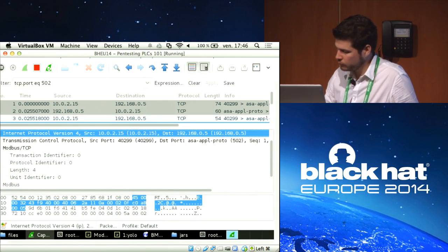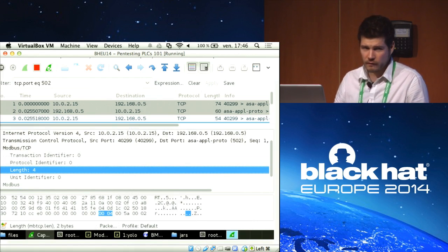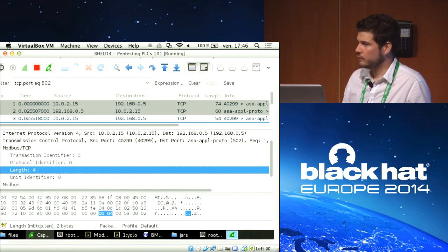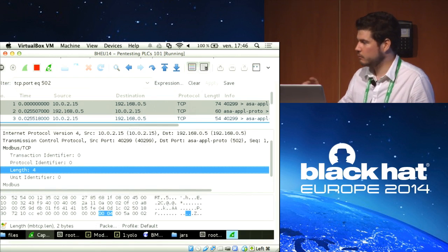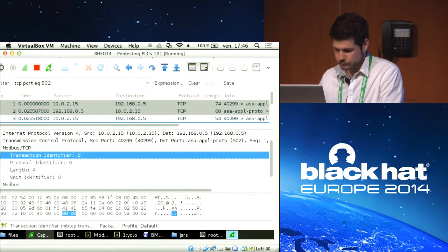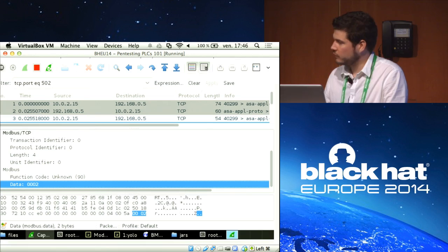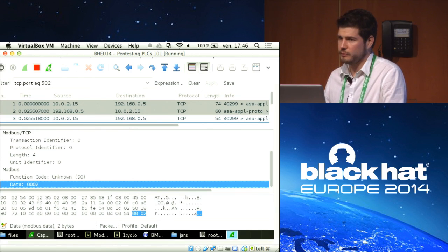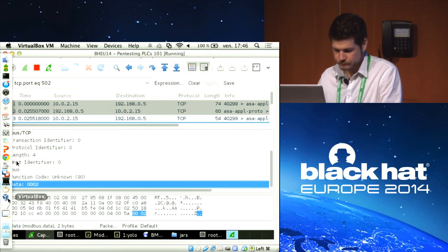And then when you set mode to run, you can put the PLC back to run. Sometimes it will not work right away because there is some kind of reservation mechanism, and if I put the PLC into stop mode, I have to wait several minutes to set it to run again, depending. So that could also be a big deal for your clients, because if all the PLCs are shut down, then you produce nothing on your plant or factory.